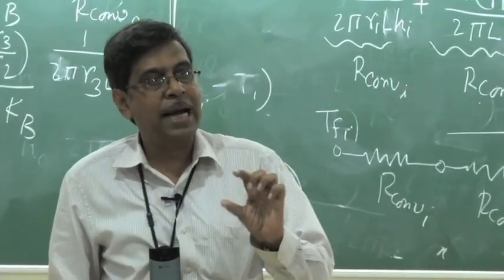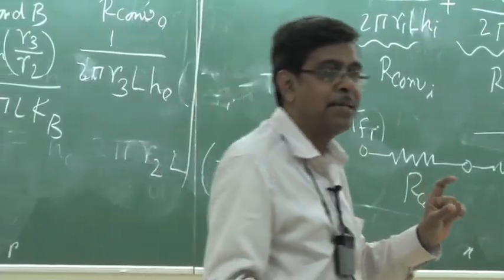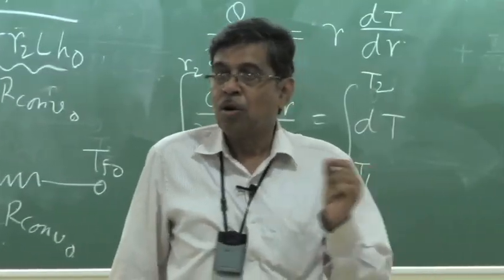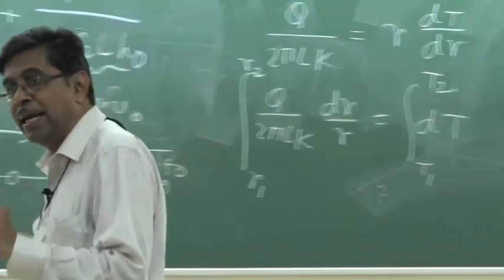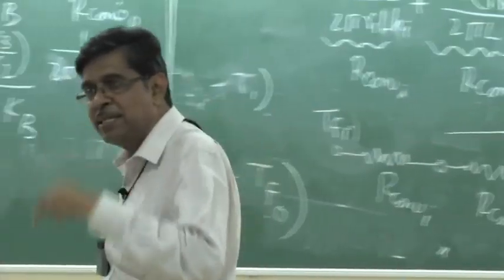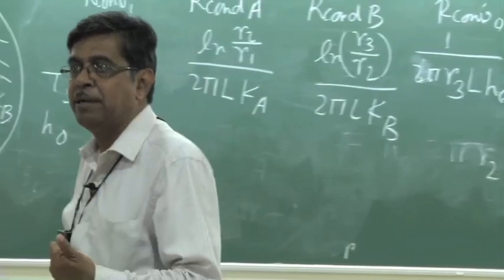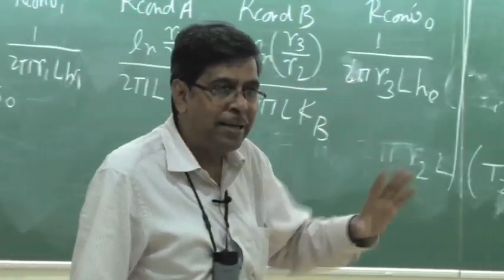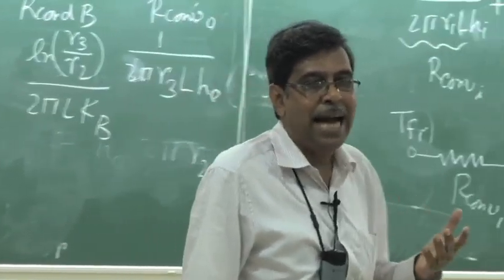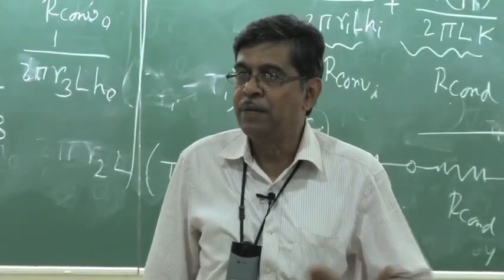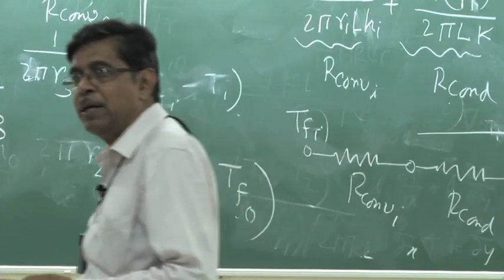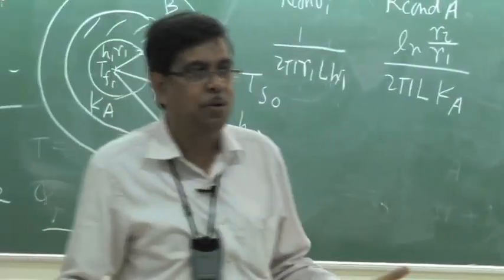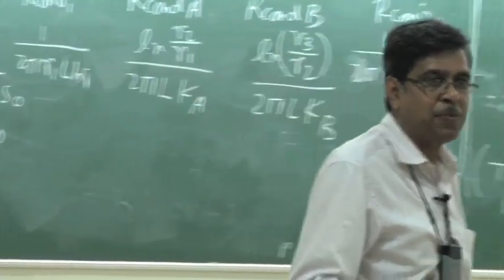You have to develop that equation by taking, as I told in the last class, the energy balance, because the concept of variable area is not there, because it is integrated over a cross section to get a mean temperature effect, or the temperature being uniform but area is varying. That part will not be manifested if you straightforward take from the heat conduction equation. This is a very general mistake in student days. I tell you, a teacher always tells his experience from student days.